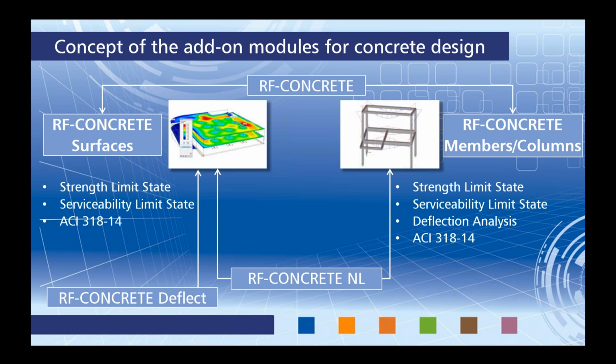So the concept of the add-on modules for concrete design. Our main program RFEM is where you're going to be doing all of your loading, your modeling. You can apply your load combinations according to different standards. We integrate with BIM software such as Revit, Tekla. And you can also run a full analysis in RFEM. So if you're just wanting the internal forces such as your moments to do your reinforcement design by hand, then by all means you can do this in RFEM alone.